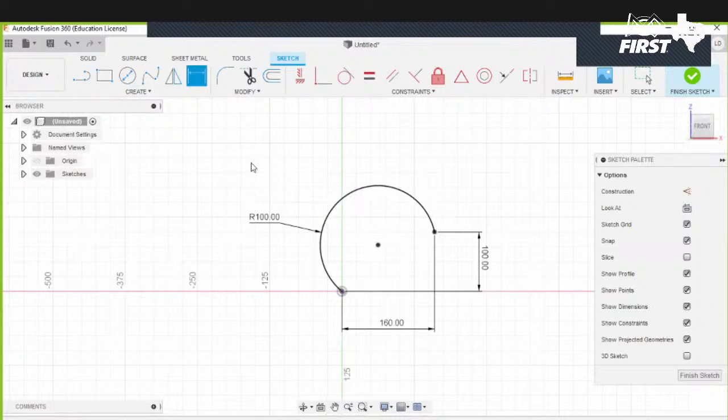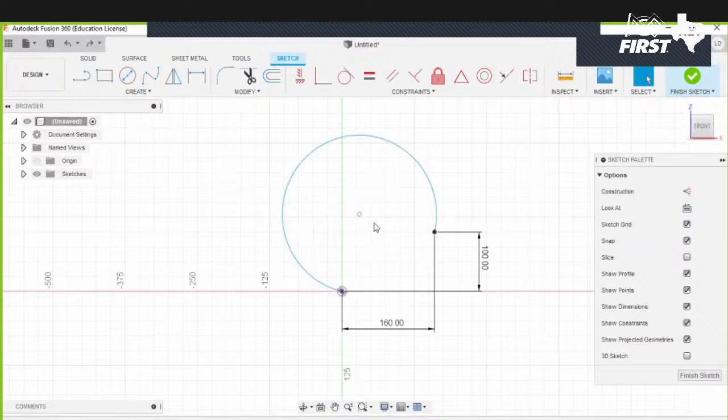That's one option. The second option is to constrain this center point. So what we can do is make a dimension of the center point to the centerpiece and do it like a combination of the two, both a y and an x, like a diagonal. Click it, fully constrained. I like the way it is, for example. We click enter. There we go.